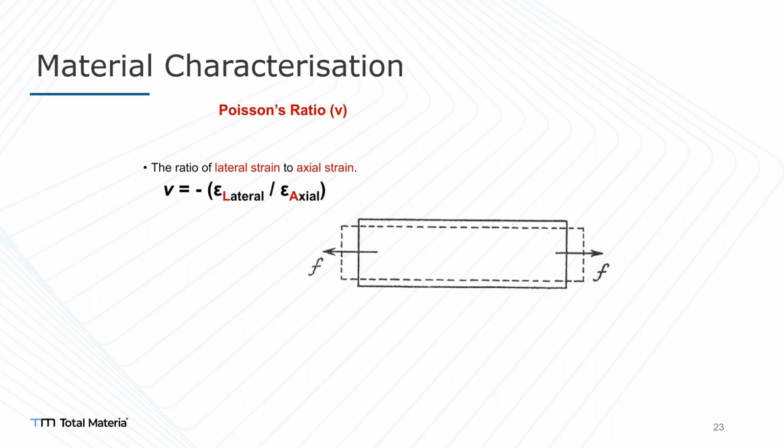Sorry, but it means that they're compressive. If you have a Poisson ratio, that means this is a compressive material, so this should be elastic. Elastic, not plastic. This is the point. Yeah, of course. I think it's worth mentioning. After the elastic limit, you're not dealing with Hooke's law, because all these equations are for Hooke's law. Incompressible material models, which are Lévy-Mises equations, will go in that area.